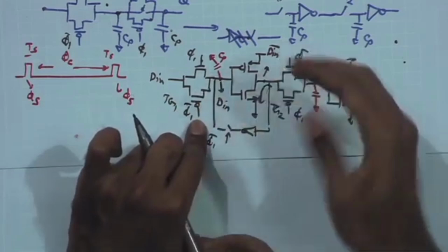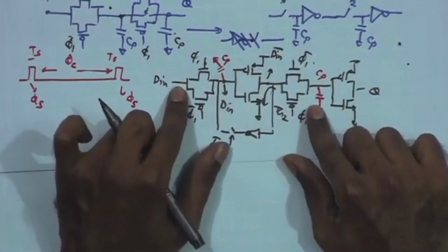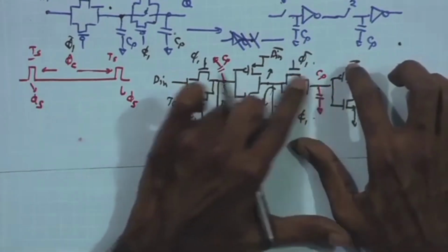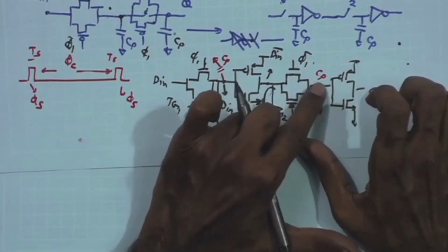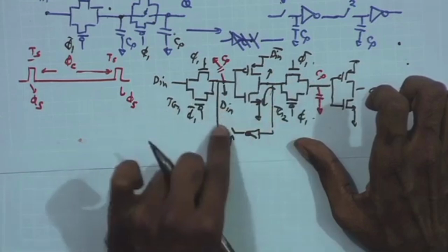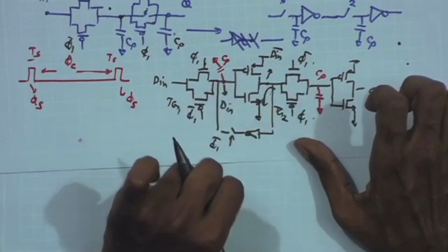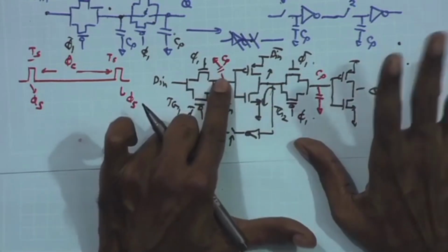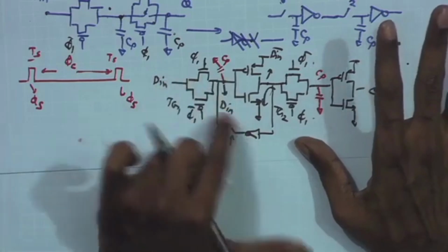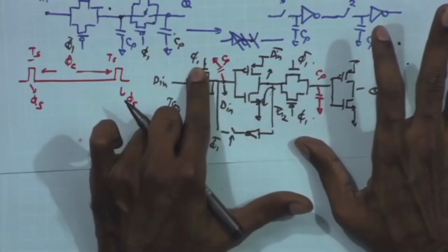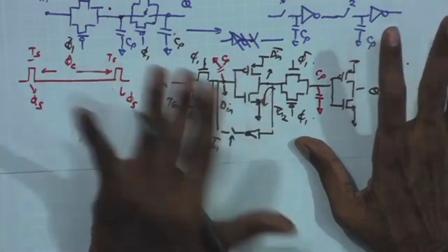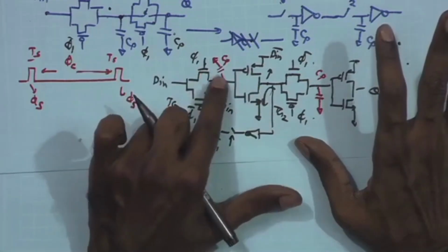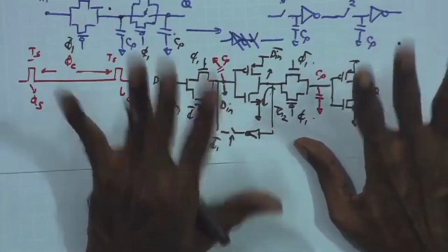More severe conditions occur when you have the clock overlap, and you can have the logic stored over here trying to propagate through this inverter into this particular node. So, I would like this node to be dictated by the D in when the phi 1 phase is on and not by this path. This is activated only when required, when this data stored over here is supposed to be retained.